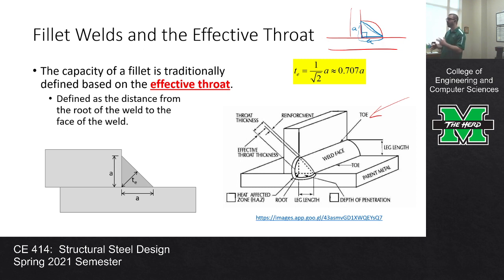There's 3 melted parts. There's part A, part B, and the electrode. And so you're melting all of that into one big old pool, and then when it solidifies, it's all one part, okay? So in order to have a quality weld, that weld has to penetrate the plates a fair amount so that you have a strong joint. That's what we mean by penetration.